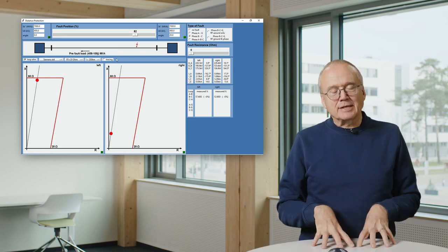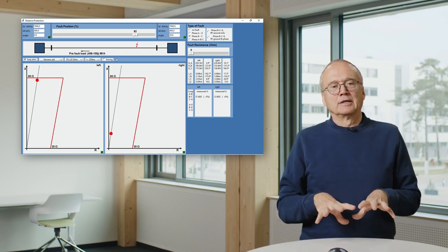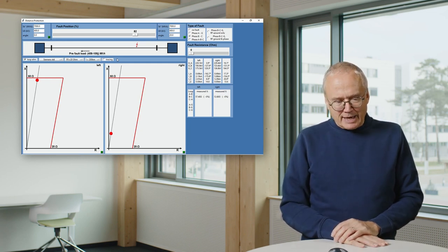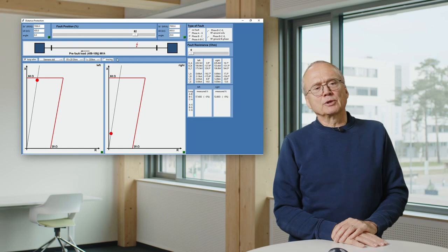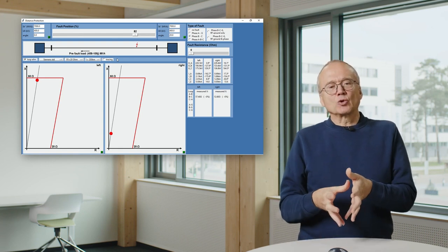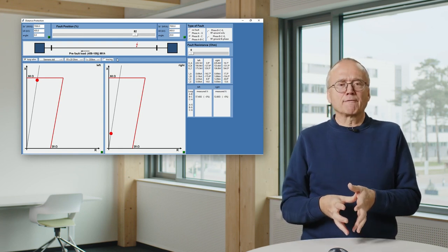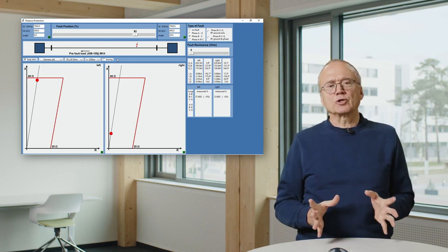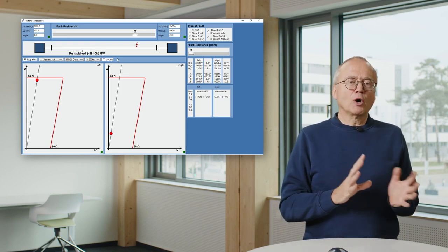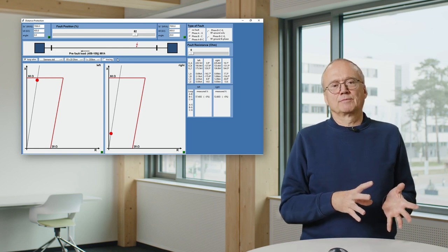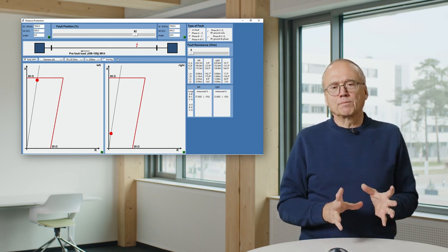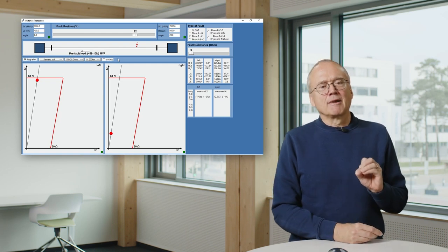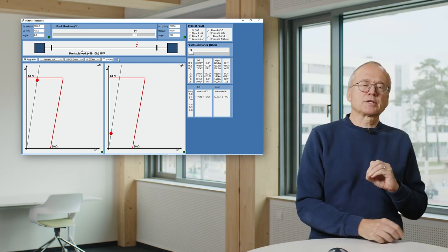As I mentioned, that is the behavior of the standard distance algorithms. Theoretically, it is not possible to really take into account and to compensate the effect of the fault resistance completely, because if you write down your equations, you have more unknowns than equations. So theoretically, there is no possibility to solve that properly. But you can do some approaches.